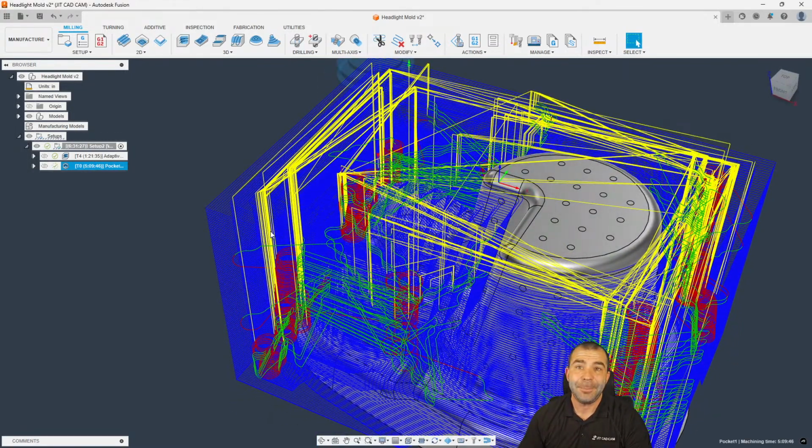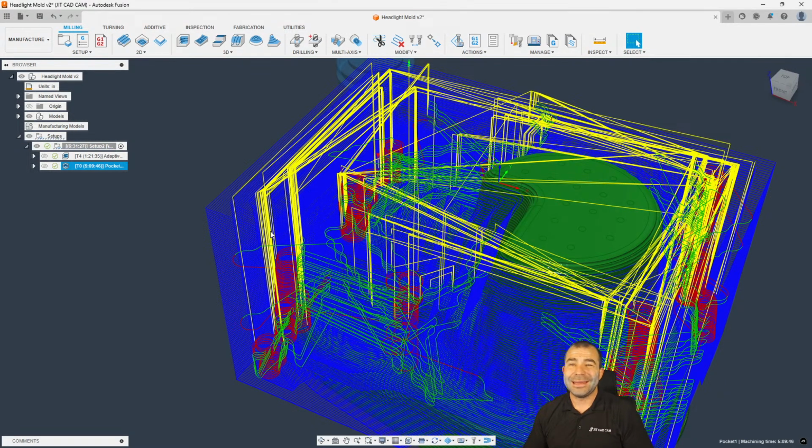But as you're going to see here, we're going to be able to go in and rough out this part. What's happening is this is much more comparable to a mower deck, right? So the idea is that because you're taking shallow step downs, you can take a much wider step over. And in theory, although your volume of removal is less, because we're only going, in this case, probably 0.95 step over and 100 thou step downs, it's less material, but it's also less torque at the end of the day.